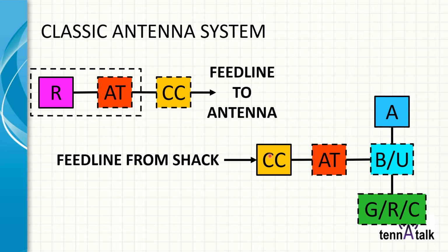And as we'll see later, don't get confused between current baluns, which is the current choke style, and a voltage balun, which is used to convert one impedance to another. So I want you to see and think about antennas as a system.